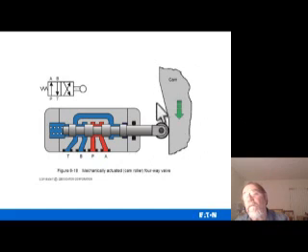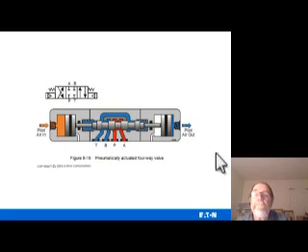This is something where the direction control valve is controlled by moving parts on a line or in a machine. That's usually like a cam follower system. And then this is a solenoid on both ends. This is what it looks like. Basically, it's a four-way, three-position valve, spring loaded and solenoid actuated on both ends.